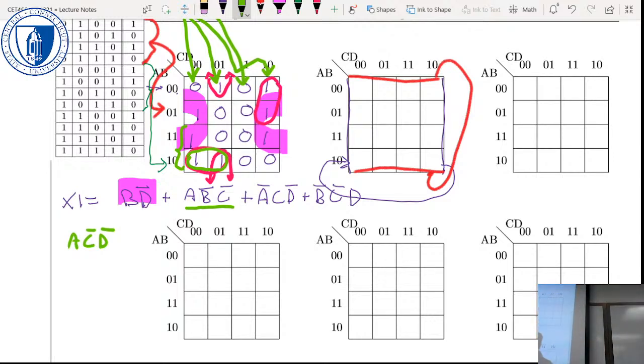Deborah, what's up? Can you just do 2 groups instead of mixing the 4 groups or 2 groups together? Sorry, say that again? Can you just do grouping them into 2s instead of mixing and grouping them into 4 and 2? I could, but I wouldn't get the simplest expression. To get the simplest expression, I need to group as many as I can to start with, and then cover all the others. So it's not wrong if you do it in 2 groups.